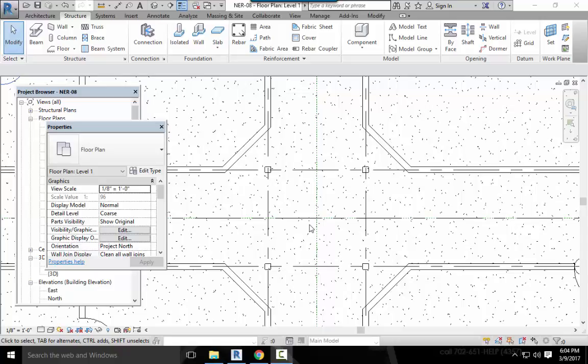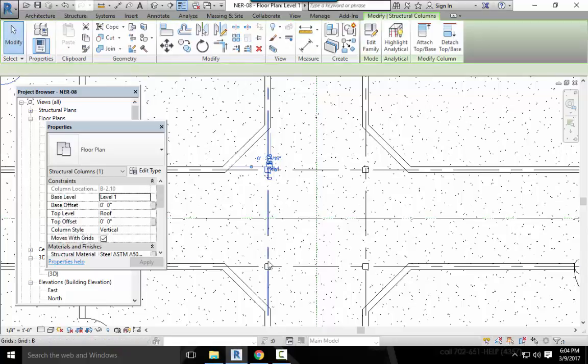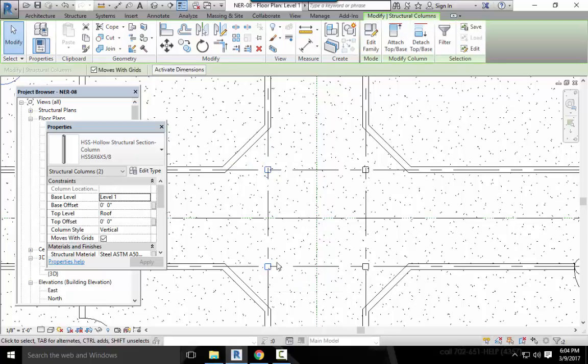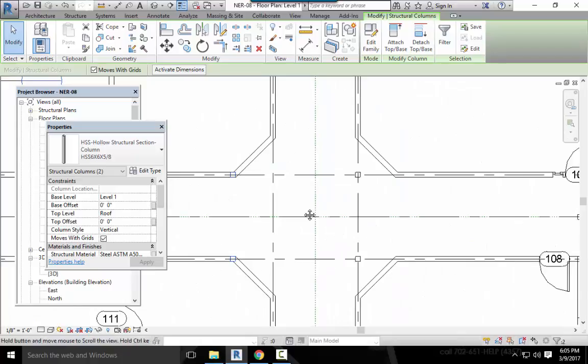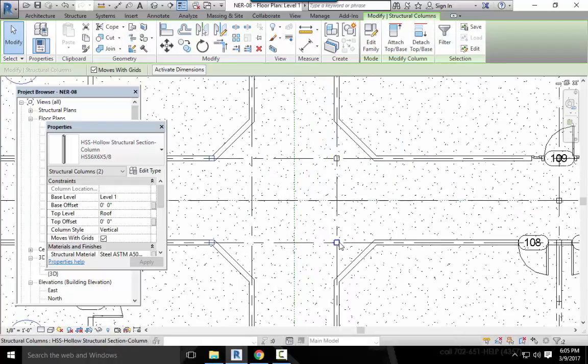Item 1, zoom in the middle of the east wing of the corridor intersection. Select the two columns to the left of the corridor shown in figure 8.31. So this column and that column. Move the columns 4 foot to the left. And that puts them in a wall, right? Now I can either move these columns 4 foot to the right, or I can mirror these about that. Modify those any way that you feel comfortable.